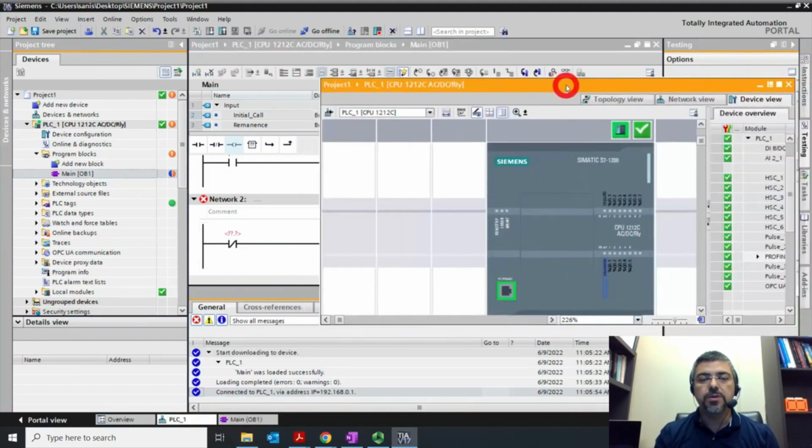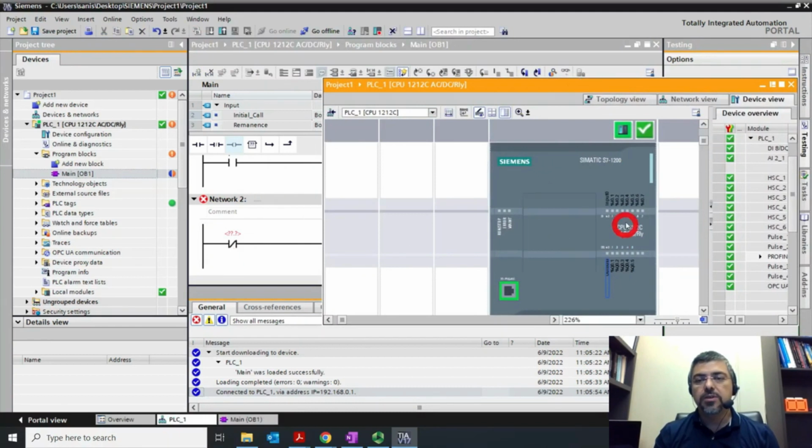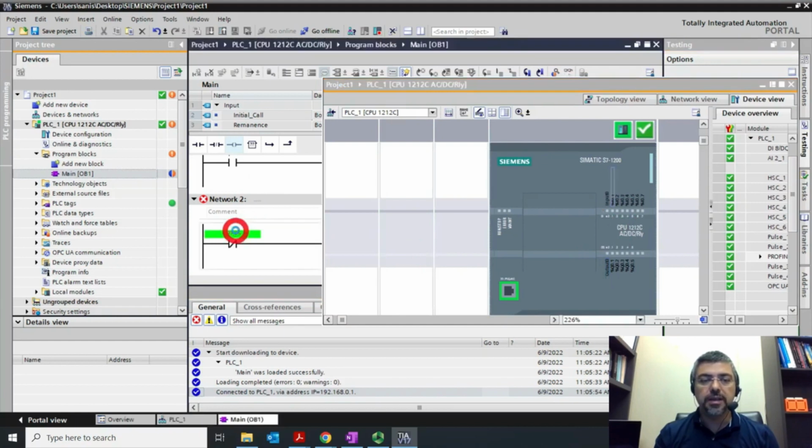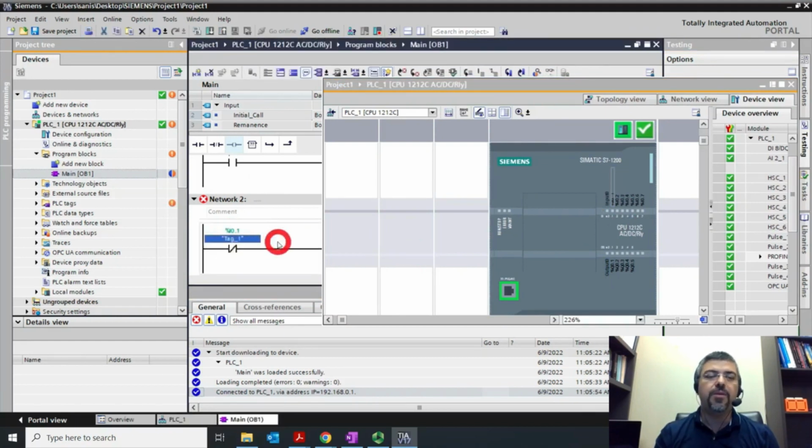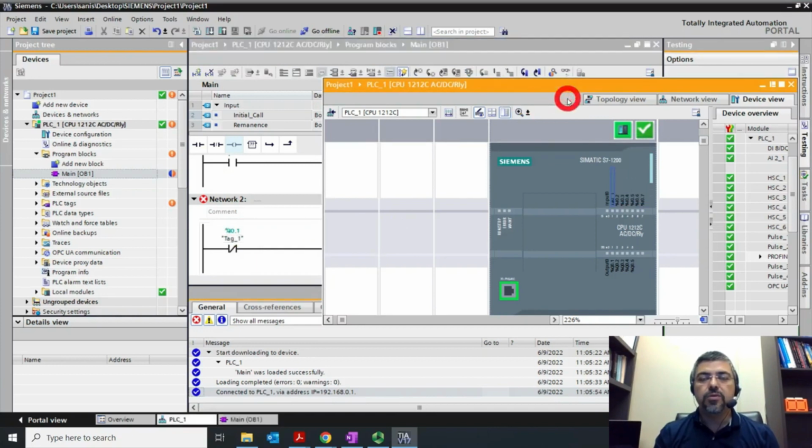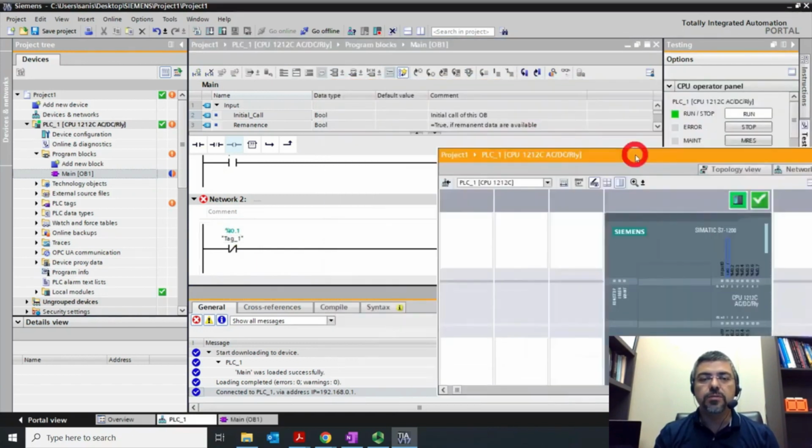We put IO0 for the first one, so let's do IO1 for this second one, set in the ladder logic. It says tag 1. I'm fine with that. Also, you could change the name if you don't like it. So see, it says which IO pin you give to this contactor. It's IO1. Same thing for the output.